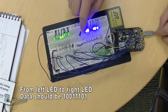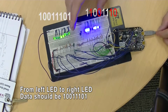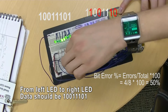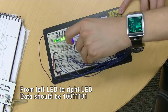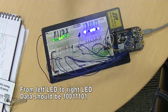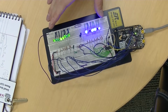Right now, as we have it running through our filter, the data line is being corrupted by the parasitics created in these elements right here, and we see that some LEDs do not match. So we have a bit error that we can calculate. If we go back to an ideal situation and move these wires so they go straight from the microcontroller into the shift register, we see that now the LEDs are the same. And this is what we're aiming for. Whenever we send a wire over a great distance, or even over a short distance at a high frequency, we want the data to be reliable.